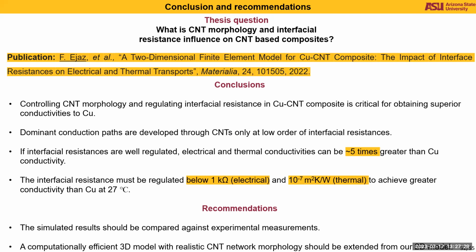And we see that if the interfacial resistances are well regulated, below 1 kilo ohm ranges for electrical and 10 exponent minus 7 meter square Kelvin per watt for thermal, it is possible to achieve superior conductivities compared to copper. However, again, this is for the ideal morphologies of CNTs, which is quite not possible yet.